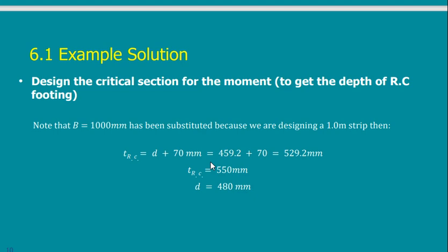But I cannot deal with centimeters or millimeters on site. It is better for us because your eye will not be able to judge mistakes otherwise. If I look from a distance to a footing and I know that it should be 50 centimeters and I find it 60, I will discover the problem even without measuring.